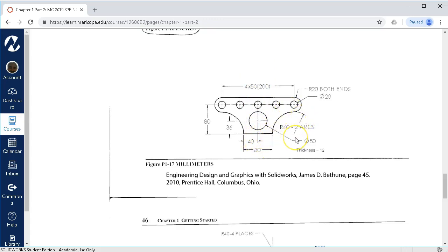We'll get the arc. There's not really an arc, so we're relying on an endpoint location, tangent-C, assuming that it's a vertical 90-degree arc, but kind of hard to tell if that's going to come off, so I don't want to make it tangent off this edge until I figure out. But coming around this way, if I were to start my origin up here, work around this way, and then bring it down tangent, come off with the line, then we'll kind of see where that center point lands while we're doing the sketch.